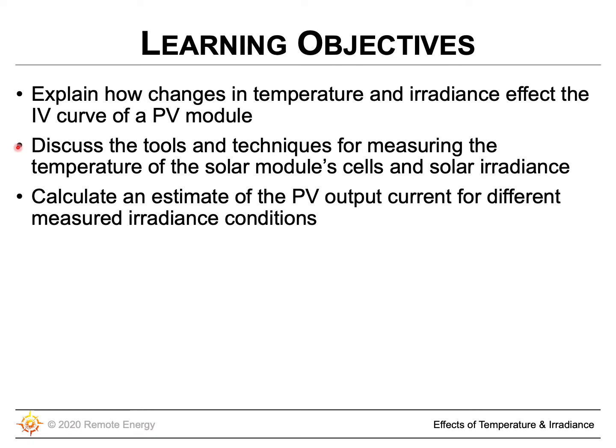Or maybe it's late in the day when you go there, so you don't have as intensive sun, and so that may affect your current. And so you need to have the tools and know how to measure that to see how those conditions will affect your PV module performance.